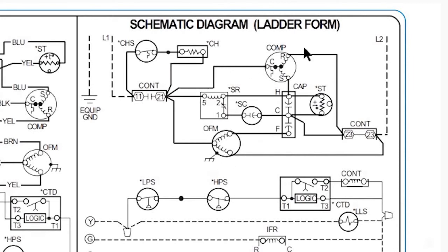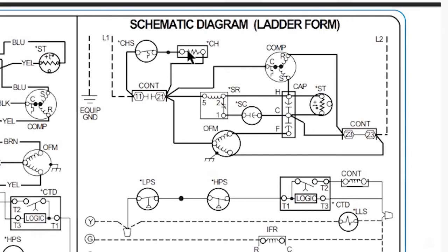So this is magnetic. When you see something like this, where it's got the more jaggedy peaks, like CH here, and then the start thermistor here, you see how those are jaggedy. That means that it produces light or heat. In this case, both of these produce heat, so they both get hot, and that's why they're jaggedy like that. They're not magnetic. Motors are magnetic, so they have the curves. Curve here in the start relay because it is a magnetic coil.